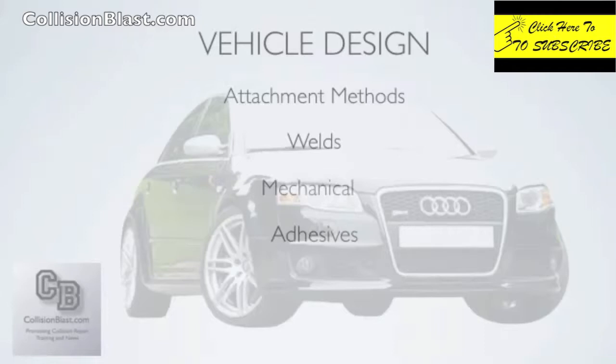And that's something else with these unibodies, you've got to consider rust. So if everything depends on these panels for its full integrity, rust is more than an eyesore. You see a rust spot on unibody parts, and it actually is weakening the structure of that car. So these adhesives help seal out moisture to prevent these vehicles from rusting.